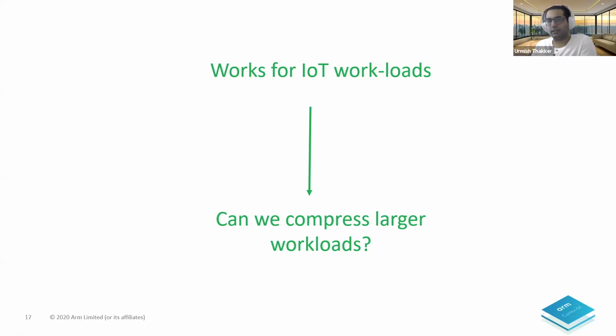Now, KP gives you two advantages. It reduces the size of your neural network and also the op count. For me, the energy consumption is a function of how many values you read from your SRAM or flash memory, and how many times your MAC units are executed. Because you are reducing the size of the network significantly, the number of things you read from flash memory or SRAM is quite small. And because your ops are also reduced by a large factor, the number of times your MAC units are used is also reduced. Given that you see a reduction in everything that actually consumes energy on a device, we should see an energy reduction, but we don't have those numbers.